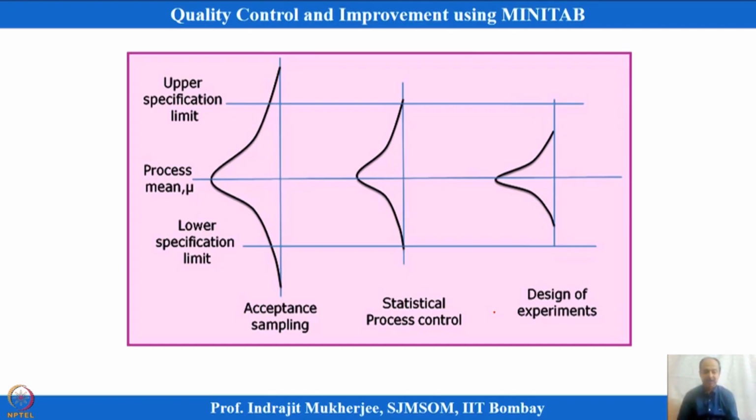So, we can take corrective action well ahead, before it reaches the upper specification or lower specification. Process variability can be reduced by using this kind of monitoring tool. He proposed the control charting technique, which can visualize the data, and based on which we can take action in the process proactively. Whenever there is a signal we will take action, and if there is no signal we will allow the process to run, and the setting conditions need not be changed.